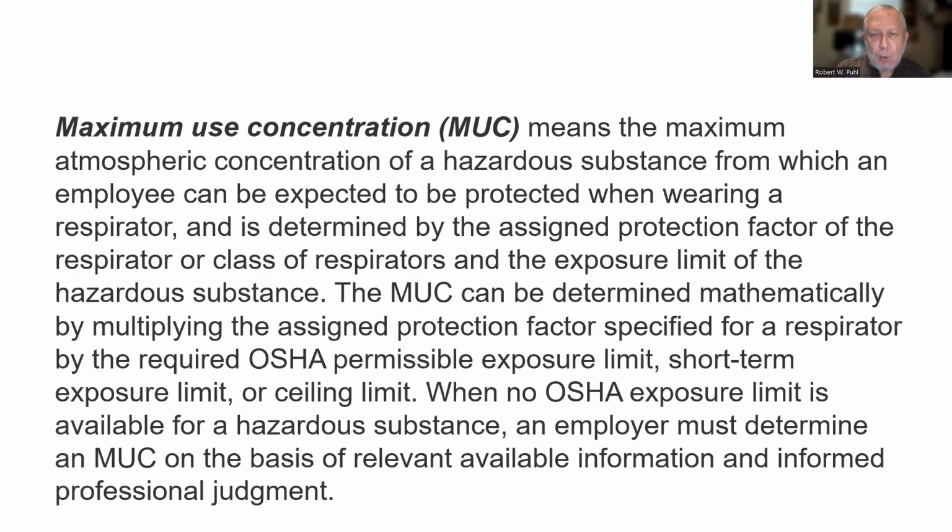Maximum use concentration, MUC, means the maximum atmospheric concentration of a hazardous substance from which an employee can be expected to be protected when wearing a respirator, and is determined by the assigned protection factor of the respirator or class of respirators and the exposure limit of the hazardous substance. The MUC can be determined mathematically by multiplying the assigned protection factor specific for a respirator by the required OSHA permissible exposure limit, short-term exposure limit, or ceiling limit.